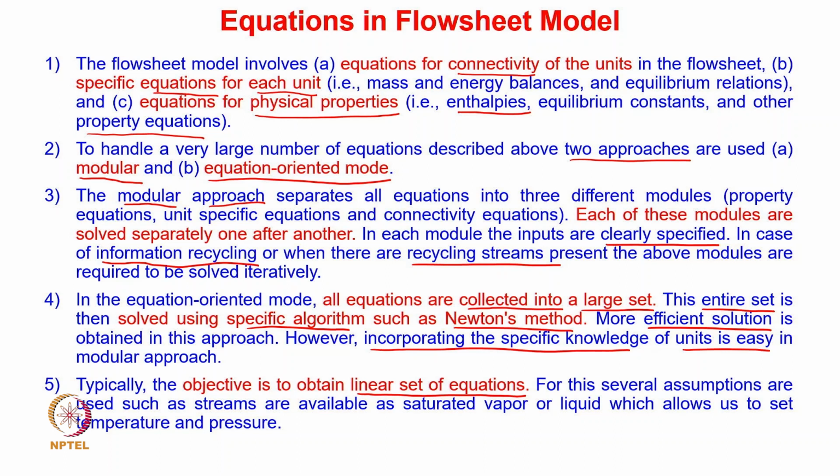But here the objective is to formulate a linear set of equations. In order to get the linear set of equations, several assumptions are used. Typically, we assume that the vapor and the liquid are both present at a saturated condition. With this assumption, we can set the pressure and temperature by using the equilibrium relations. That simplifies our analysis significantly.